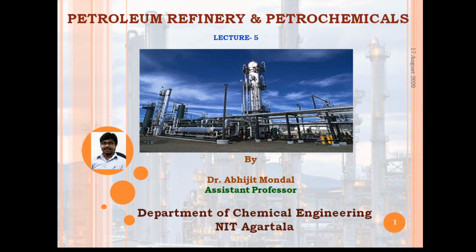Distillation under vacuum permits fractionation at lower temperature, which helps to avoid cracking of the reduced crude and coking of the furnace tube.